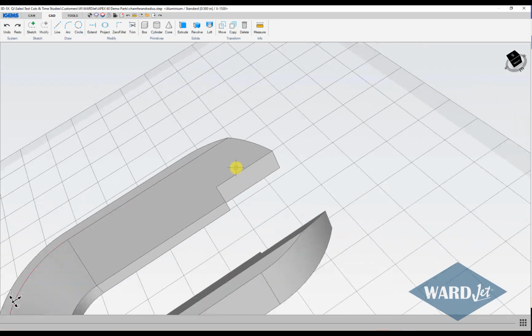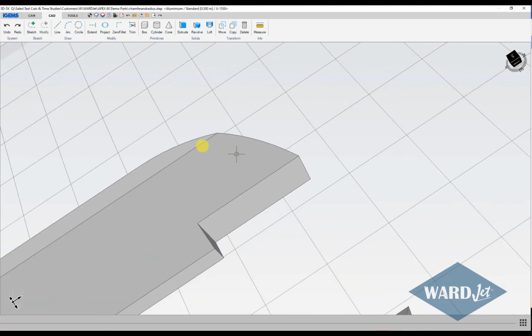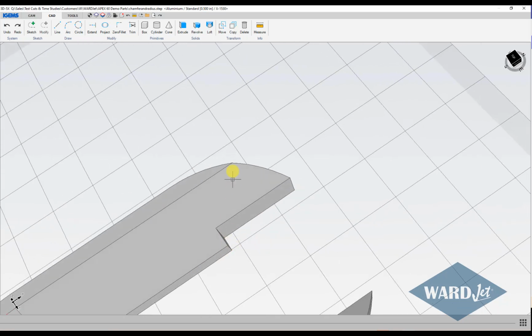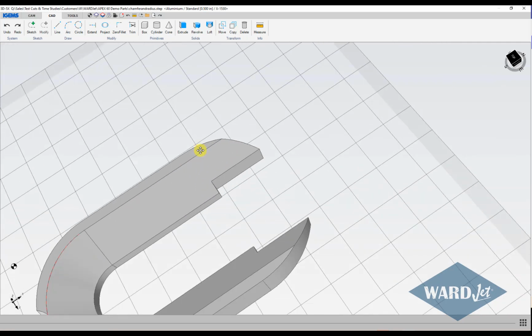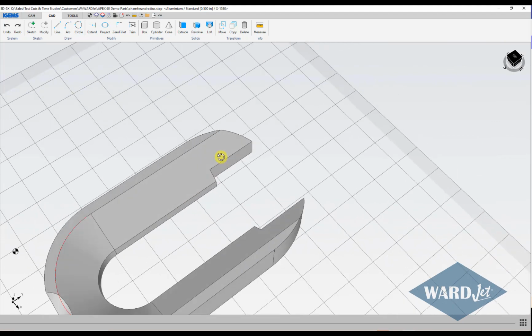Now at the other end of this bevel cut, again looking at top and bottom edges that we can select. So this can be our top edge, this again will be our bottom edge for this bevel cut here. But again, we've got this area here where there's this void where we've got no edge. If we choose this edge and then we go to connect it, we're going to end up with this connection that'll come down here at a very steep angle, and it's going to straighten up, and again it might not be the best result.